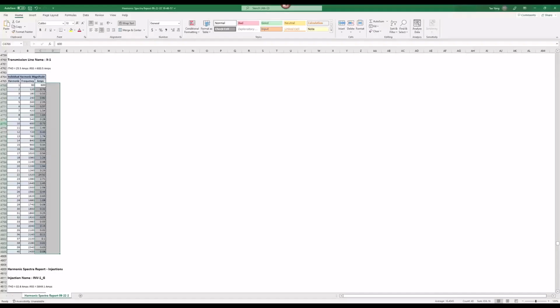Okay, next question is AC to DC. Should I be worried that the harmonics or DC portion will stop the harmonics from transferring to the other AC side? Again, AC, DC, AC, I don't think that's a problem, because all the utility cares about is the AC interface that it can see. What's beyond it is not a harmonic issue, right? Next question is about the harmonic source. We have current or voltage harmonics. How to control this?